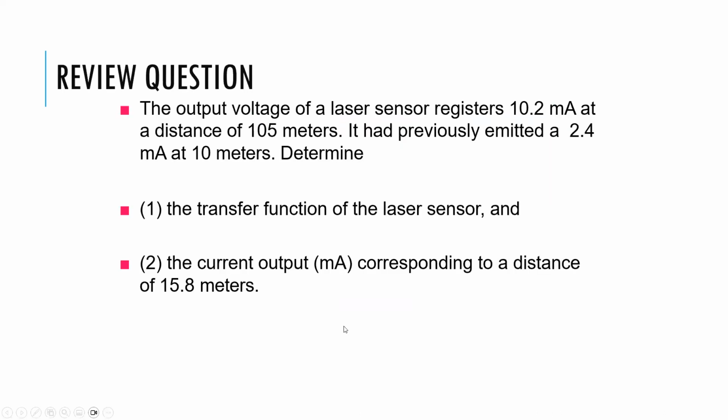And there's going to be a sample question that looks something like this. Given the output of the sensor is 12 milliamps, and so you've got the two unknowns, I mean, enough information to derive that linear relationship, and then you'll be able to give the sensitivity.